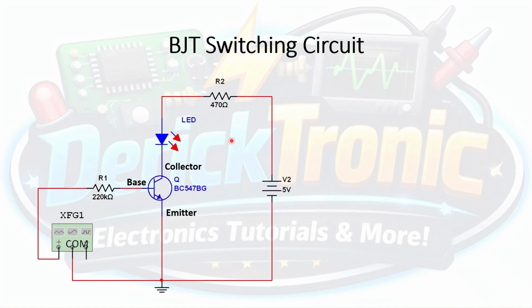Now, similar to the biasing circuit we saw earlier, the emitter of our BC547 will be grounded. The collector, on the other hand, is directly connected to a red LED, at the cathode of the red LED. The anode of that red LED will be connected to a 470 ohm resistor, the limiting resistor on the collector. And that resistor is connected to the power source, the 5-volt DC supply.